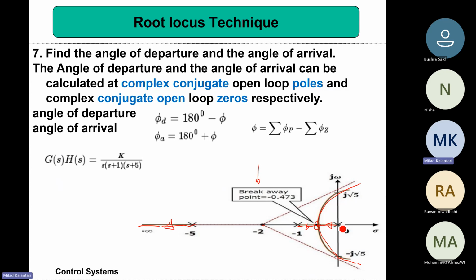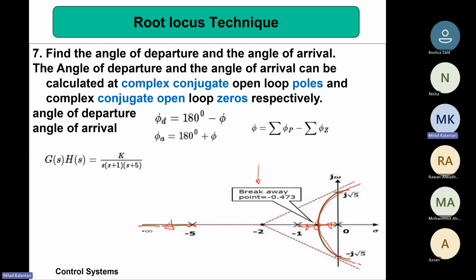So we see if k is too low, then the open loop system is basically semi-stable because there is a root at zero. But if you increase k, the roots start moving to the left, right? And then maybe the speed is still not too good in this response, because with two real poles, one next to the origin is slow, right? We don't like the root to be very close to the origin because it becomes slower to damp the response, right?